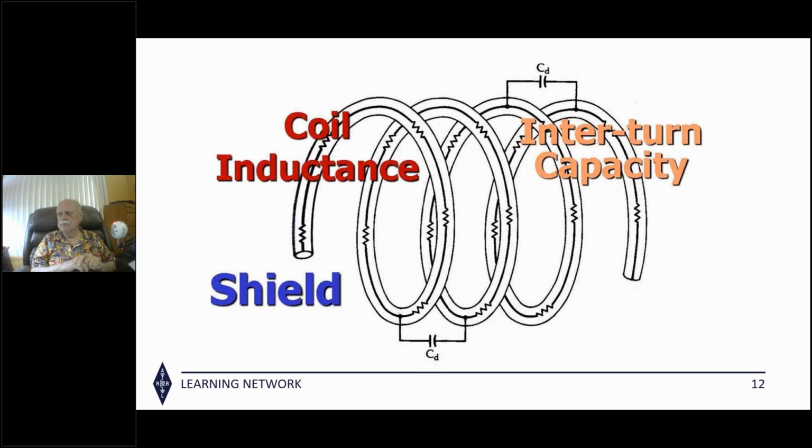With a ground-mounted vertical antenna with radials on or just below the surface of the ground, and the coax feed line running on the same plane as the radials, where should the Balun be placed? Right there at the antenna, because as I said earlier, a quarter wave vertical with radials is essentially a dipole in which the radials are acting as the other half of the dipole. In other words, the quarter wave that sticks up, the spike, is counterpoised against the radials, which in essence is the other half of a half-wave dipole. They may be resonant or non-resonant, depending upon whether they're above ground or in ground, but there's still the other half of the dipole.